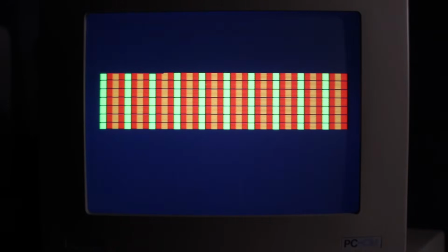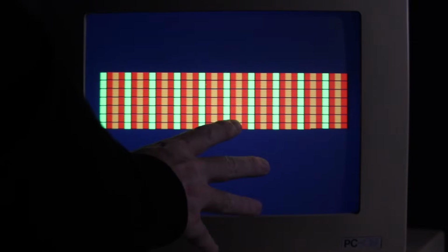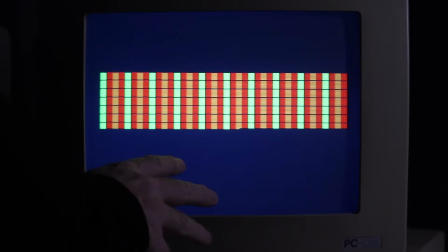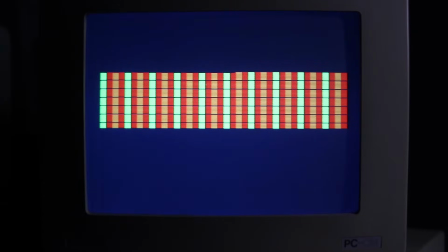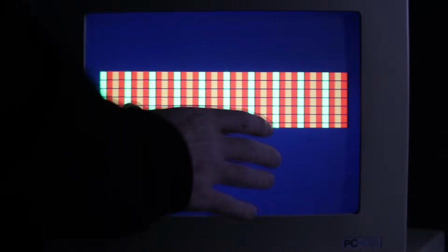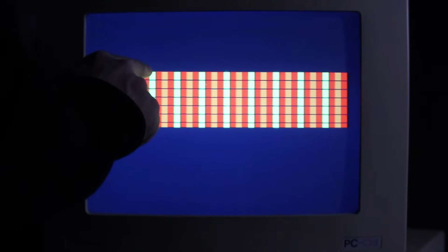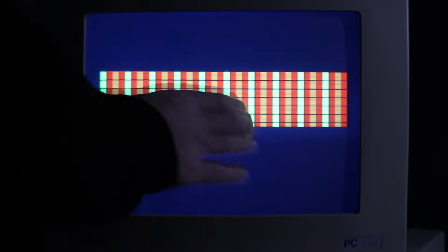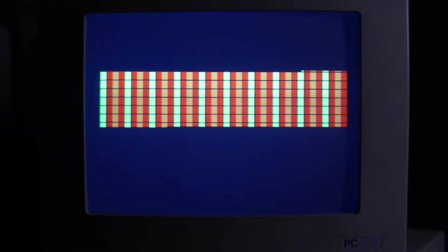But one effect you could do is to put a static image in VRAM and not change it at all, but basically only display a certain portion of that image. For example, turn the display on here, off here, and so on each line, just to display a rectangle's worth of VRAM at a time. And because we can control very precisely where the first write happens in the display cycle, we can effectively move that rectangle around, showing different portions of the video RAM.